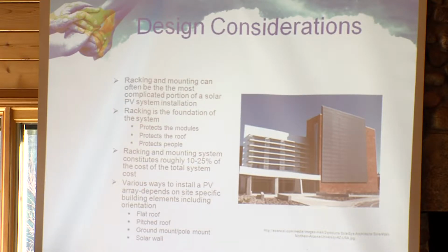I'll say this right now, just across the board, a roof mount system is less expensive, nearly 50% less expensive than a ground mount system. But there are lots of good reasons to do a ground mount system, because if you have to replace your entire roof to add the correct structural integrity just to support your rooftop installation, it might be better just to do the ground mount system if the roof is just fine, and say you just replaced the shingles or the metal roofing a year ago.